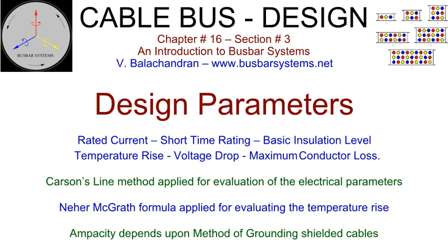voltage cable bus. In the temperature rise test, not only will the conductors not carry equal current due to the combined effect of skin and proximity, but the heat evacuation from the conductors will be different. The conductor that is surrounded by the other conductors will have the maximum temperature rise. Since the mathematical model for the distribution of current, forces, and temperature in a cable matrix is very complex, a comparison with the test and field data of a near equivalent product will be most useful.